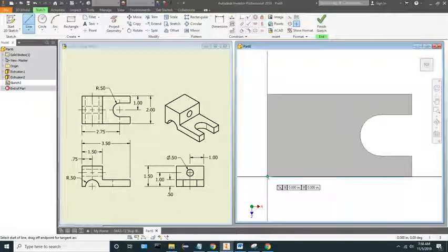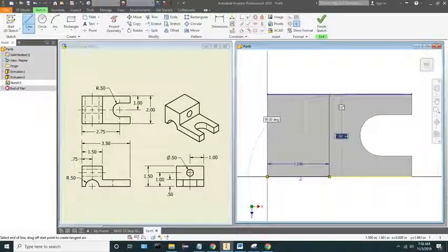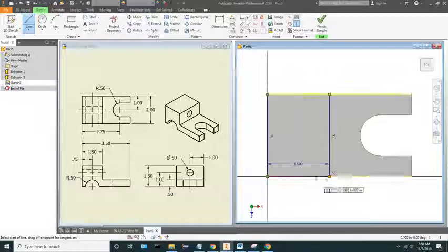So I'm going to start in this origin corner again, go 1.5, I might have said 0.5, it's 1.5 across, and then up to the other side, and it'll snap at that point, and then you can snap at this axis point, and then back at the origin to make your enclosed figure.